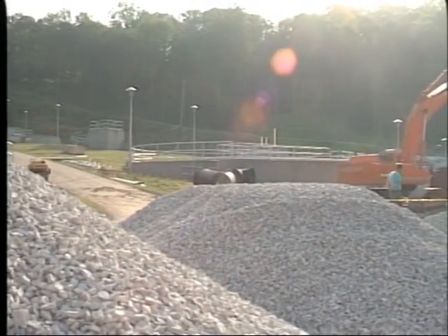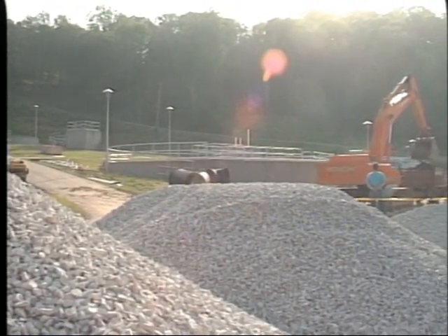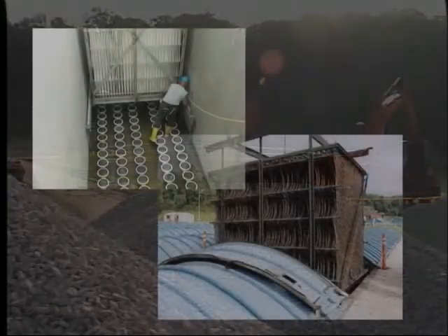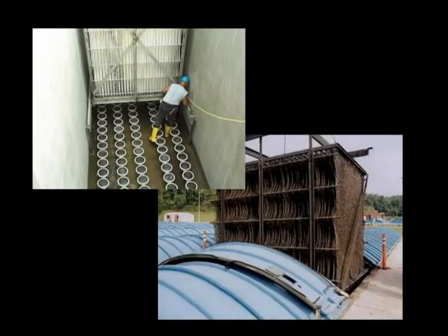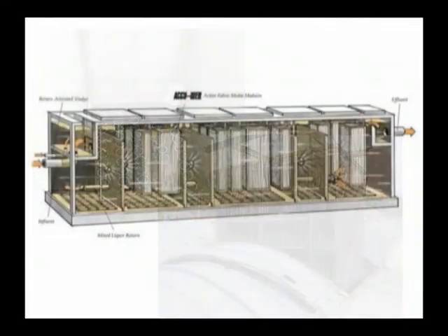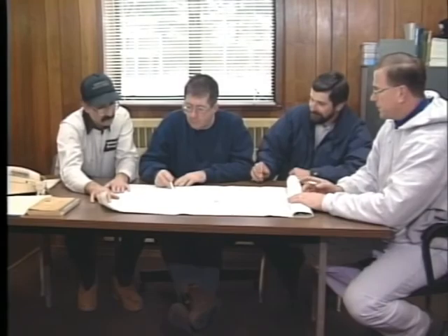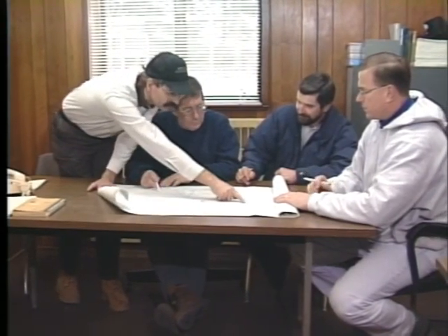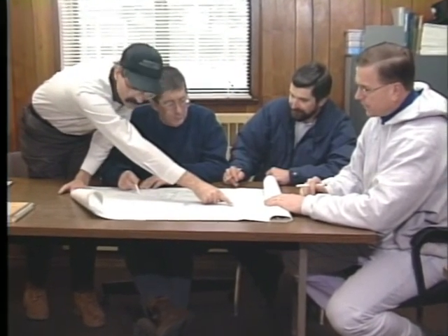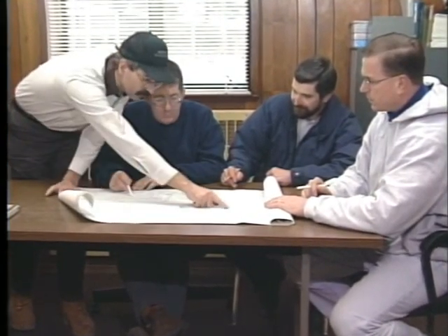It may be necessary to add tanks, or in the case of some activated sludge systems, add fixed film media to the aeration tanks to increase the capacity to nitrify. In any event, carefully review your options with your engineers before making any significant investment. Remember, design changes at a treatment plant require prior approval by DEP.